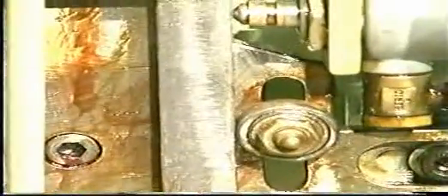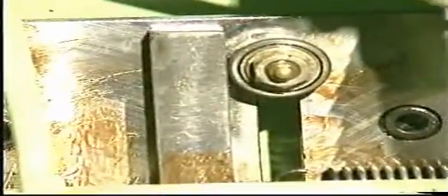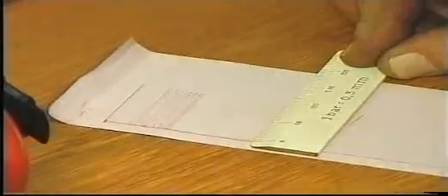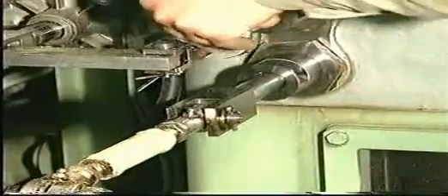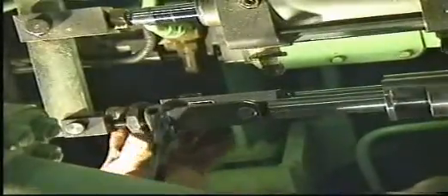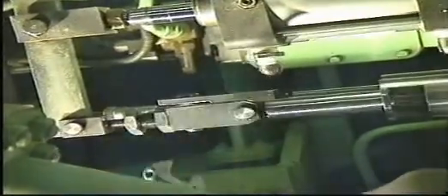At this load, the steel rod must touch both pivoting points. If the rod does not touch both pivoting points, adjust the rod in accordance with step 2.3 of this film. Measure the maximum combustion pressures of each cylinder. Adjust the links or disconnect and lock the VIT racks so that the maximum combustion pressures, corrected to ISO ambient conditions, are uniform and have the required values.